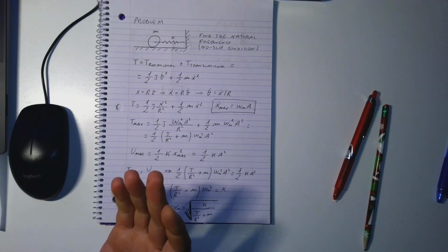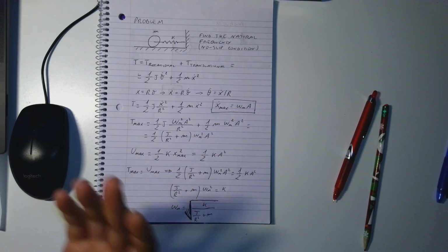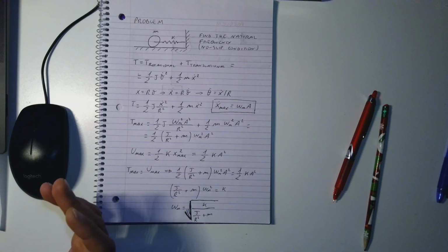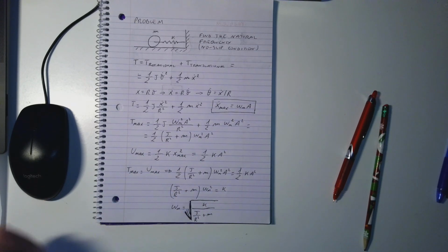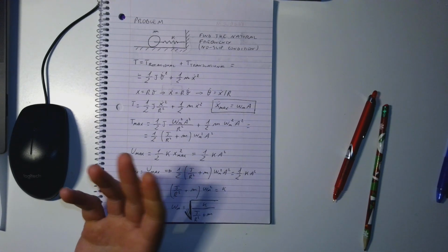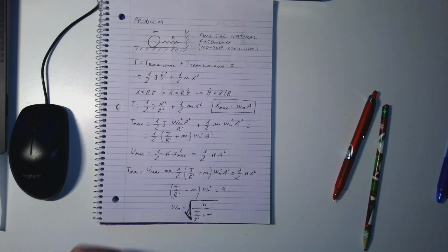Of course both methods must bring you to the exact same result, unless there is something wrong in the steps of one way or the other. Basically you take the summation of kinetic and potential energy, equal this to a constant, and then you differentiate, it becomes zero, and you obtain the equation of motion.